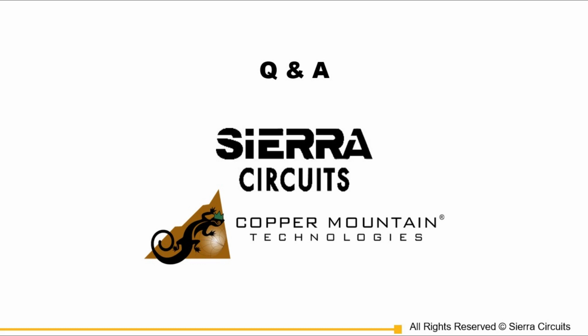I think the question is basically, if you had a 25 ohm driver, could you use a 25 ohm line? Most drivers have a much lower impedance than 50 ohms, and you generally have some kind of series 22 ohm resistor to avoid ringing, basically to avoid reflection at the source end. But you could also have a 25 ohm line. There's nothing wrong with that.